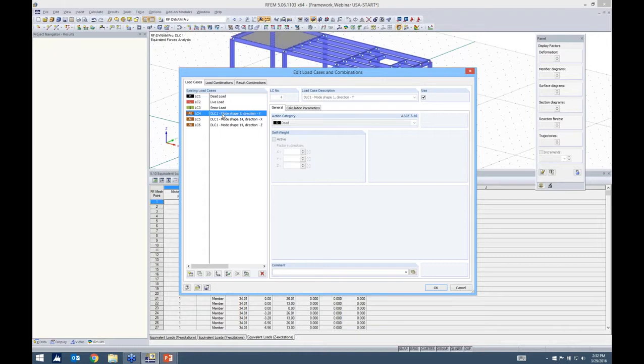But now we have some mode shapes, and we have kind of a special case here for this structure because we had those two dominant modes, mode shape 1 and 14, for all of our X, Y, and Z directions. This is pretty rare. Usually you're going to have several mode shapes for all directions in order to go ahead and reach that 90%.